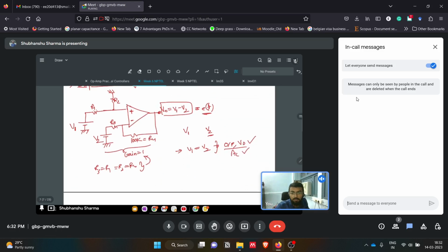Based on that, we also realized CMRR, that is common mode rejection ratio, which is given by AD by AC. AD we know is 1, and AC we derived using the output we were getting. We can get AC using V0, which is (V1 plus V2) by 2 into AC. So whatever voltage we were getting at that point, from that we can calculate AC. Based on that we calculated the CMRR, and we got some 58.8 dB of CMRR.